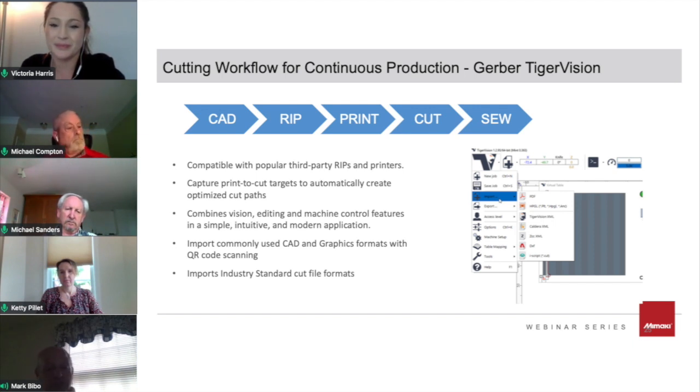So not only are we reading the dots and knowing where to do the cutting, some materials will stretch, just the nature of the material. So if the print tends to stretch a little bit, we actually run a compensation routine in software. By using the dots that we read in with our camera and knowing where the cut lines are, even if the material does stretch, our software is able to provide information to our cutter to provide a very, very accurate print-to-cut registration.